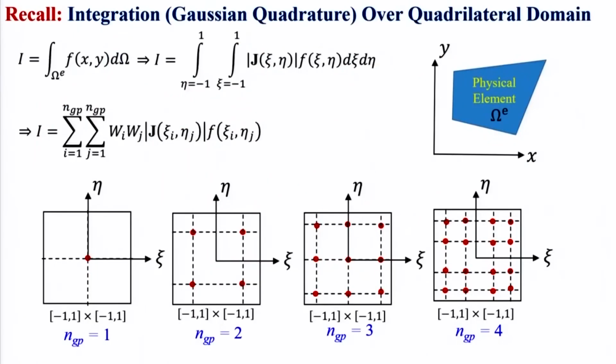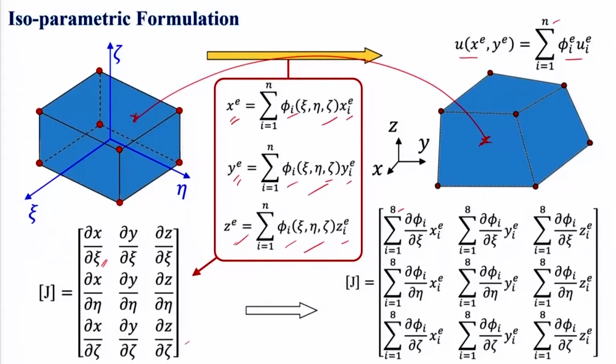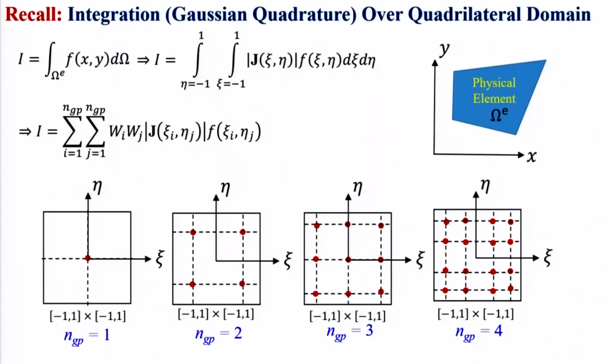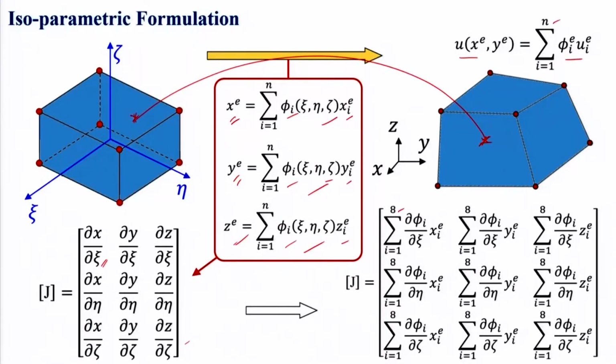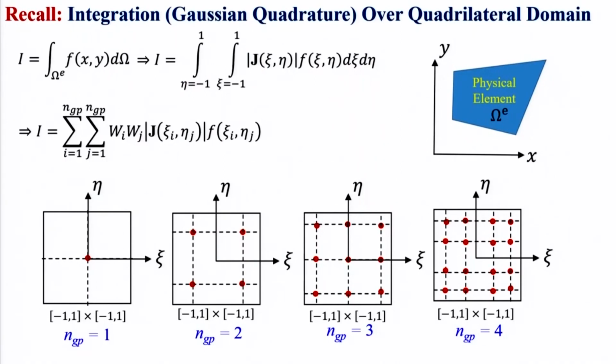Okay. Now, once we have this Jacobian, eventually we have to write the element equation, and after the element equation is written, then globalization, then solution, whether it is 2D problem or 3D problem, those things are almost similar. Now, writing element level equations requires this mapping, the isoparametric formulation, right? Another thing required is the integration.